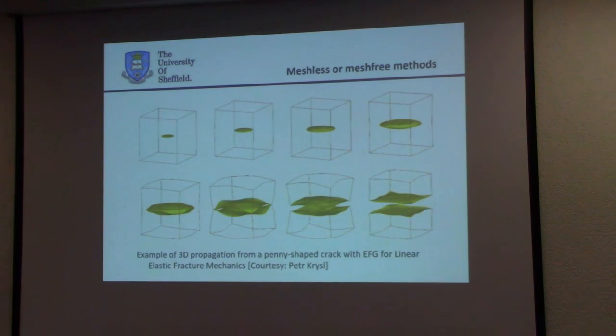Well, this is an example of computation. It's a 3-dimensional computation. Here you have a linear elastic fracture mechanics calculation with an initial penny-shaped crack in a square cube, or in a cube. Yes. Here you see it growing and growing, and here you see how it finally goes into 2 separate bodies.